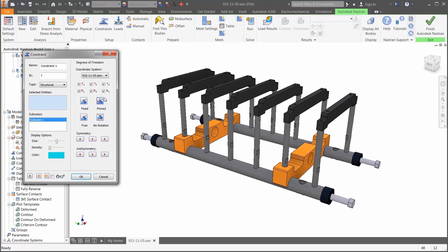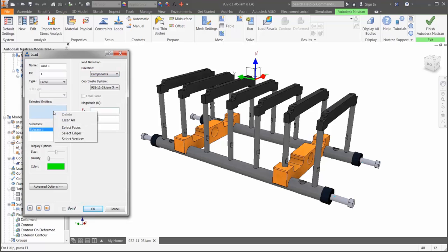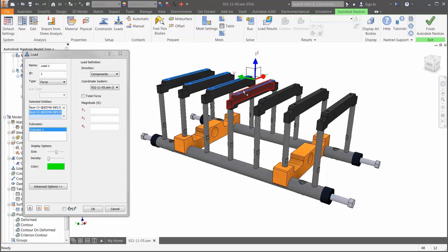We can then begin describing the behavior of the assembly. How is it held down, and where are the load conditions applied? Constraints can then be used to simulate the 4 locations where the fixture is attached in the main assembly. And we have the load that is coming down from the actuators and the fixture above. In just a moment, we will observe the impact of these forces on the stress and displacement of the assembly structure.